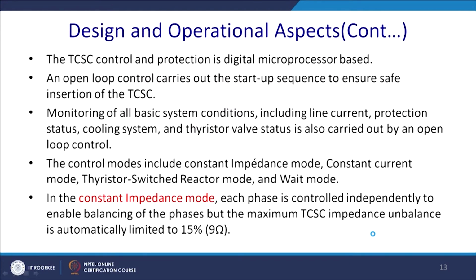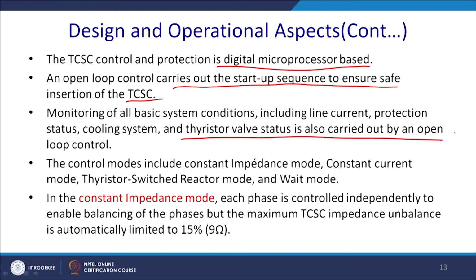The TCSC control and protection is digital microprocessor based. The open loop control carries out the startup sequence to ensure safe insertion of the TCSC, and monitoring of the basic system conditions, including the line current, protection status, cooling system and thyristor valve status, is also carried out by the open loop control.